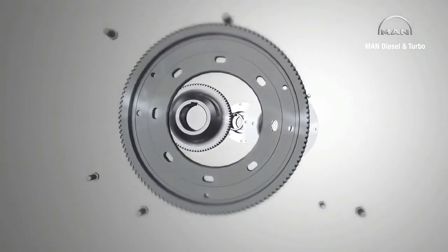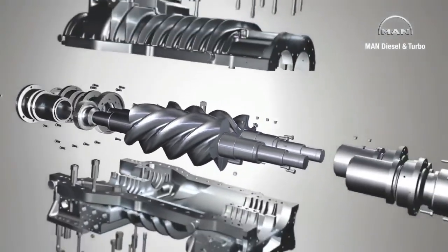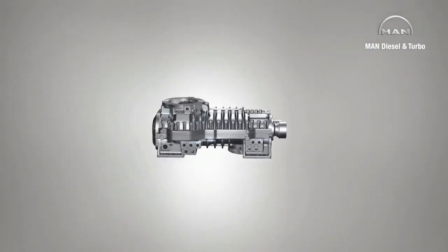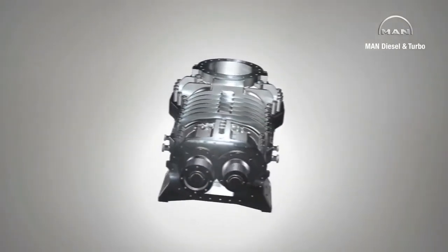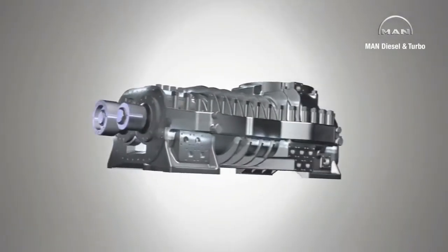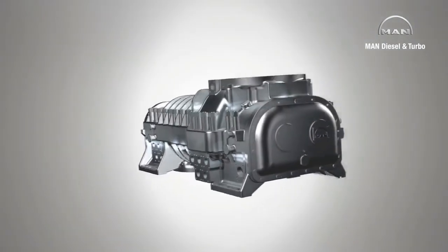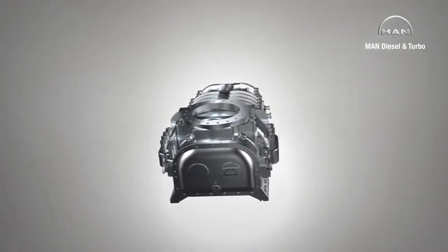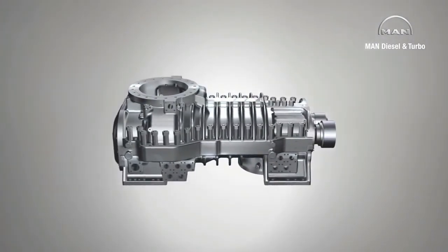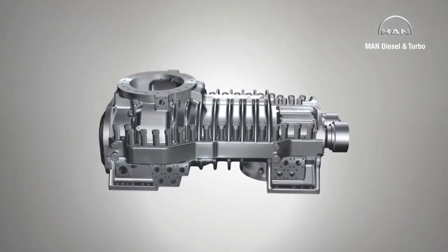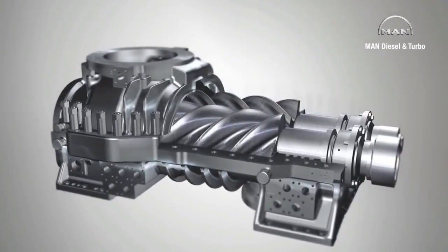MAN manufactures tailor-made process gas screw compressors for customers, a modular system of tried and tested components guaranteeing the utmost reliability. Depending on its size, a compressor stage can suck in and then compress volume flows of between about 200 and 100,000 cubic meters per hour. All screw compressors operate according to the basic principle of a positive displacement machine, whose key element is a pair of spiral rotors.